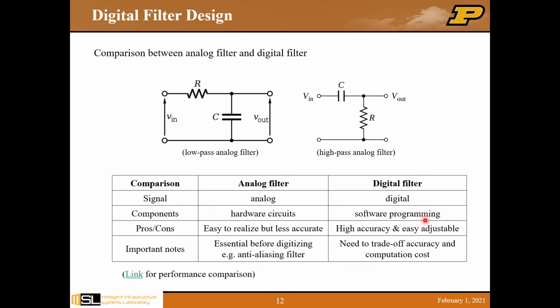A digital filter is easier to program and more powerful for applications, but we need to think about the trade-off between accuracy and computation cost, especially for real-time data processing implementation. If the performance requires more complex behavior, that requires more memory and more time to compute. In that case, there's a concern about whether we can realize all the analysis within one step, such that the entire process can be implemented in real-time analysis.